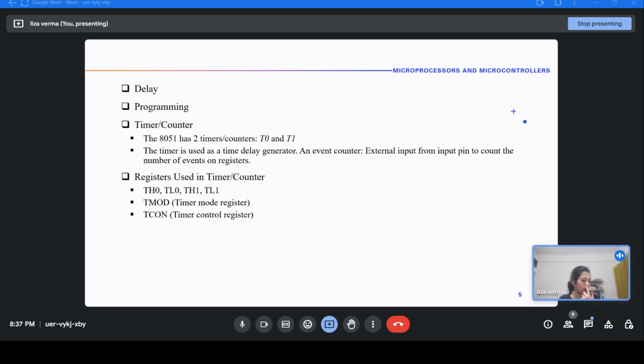Then M2 is an 8-bit timer counter with a reload. Let's say you want to keep counting. All of these other modes, M0, M1, and M3, are single modes. You load the counter value and they count until FFFF, whatever the value is, count back to 0, an overflow is generated, and they stop. Only M2 is the continuous timer.